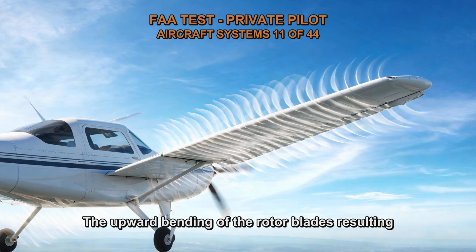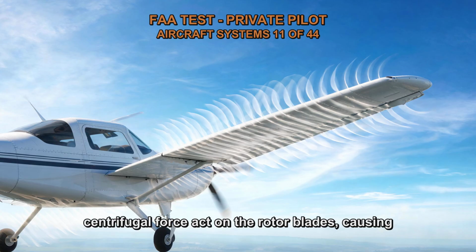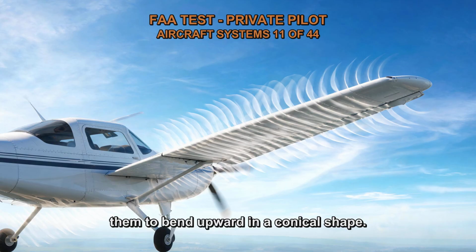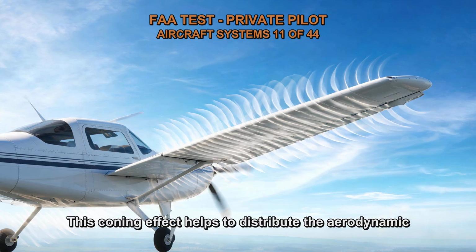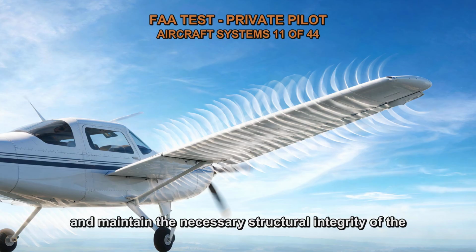The upward bending of the rotor blades resulting from the combined forces of lift and centrifugal force is known as coning. As the rotor spins, the lift force and centrifugal force act on the rotor blades, causing them to bend upward in a conical shape. This coning effect helps to distribute the aerodynamic loads evenly across the length of the blades and maintain the necessary structural integrity of the rotor system.